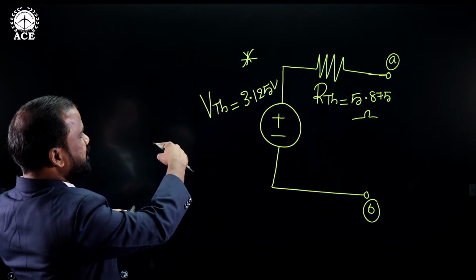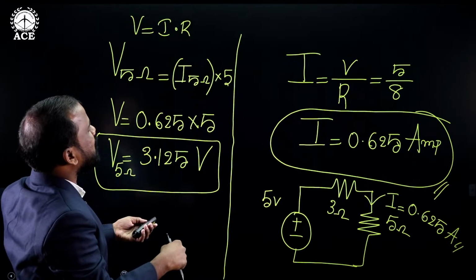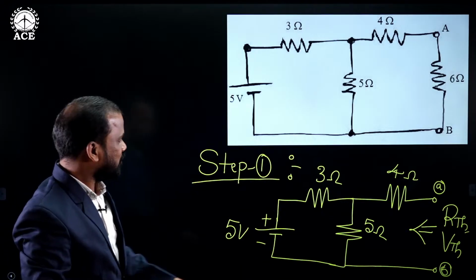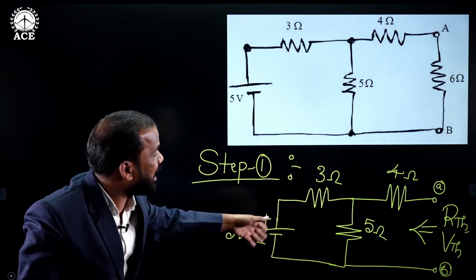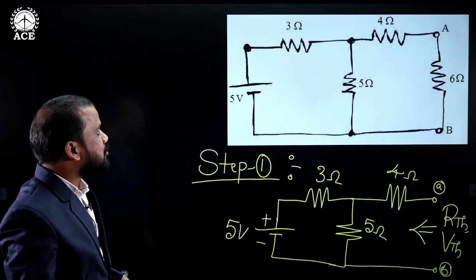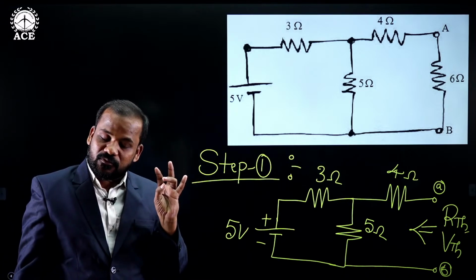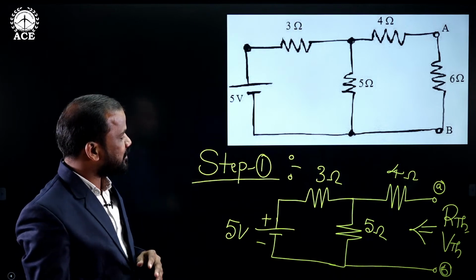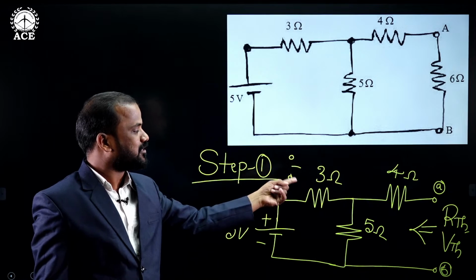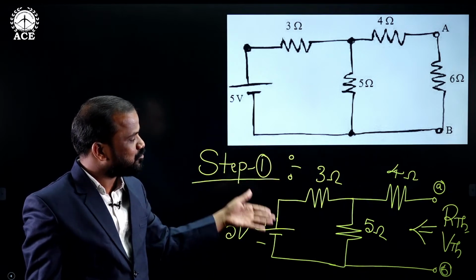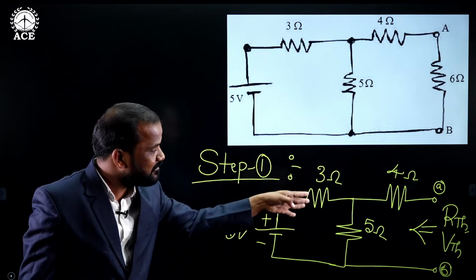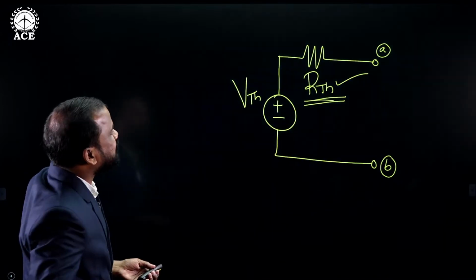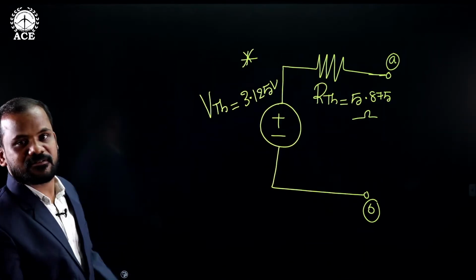Okay, it means that this equivalent circuit is replacing instead of this thing. Got it, I think? Yes or no? This two-terminal linear network can be replaced by a two-terminal equivalent circuit consisting of Thevenin voltage and Thevenin resistance. But to replace that particular equivalent circuit, we require the calculation of Thevenin resistance and Thevenin voltage. We calculated these two values across the open terminals where we disconnected the load, so that I can directly replace this complete two-terminal linear network by this. I think you are clear.